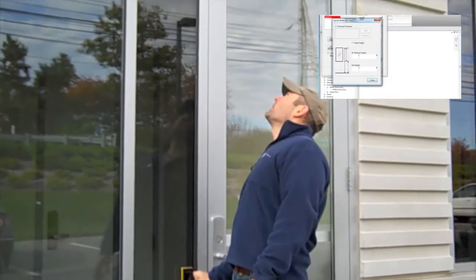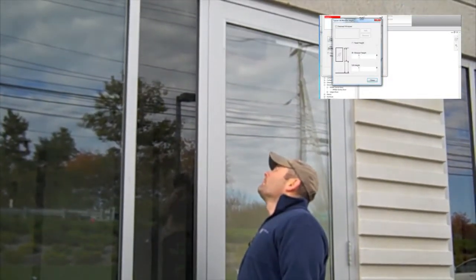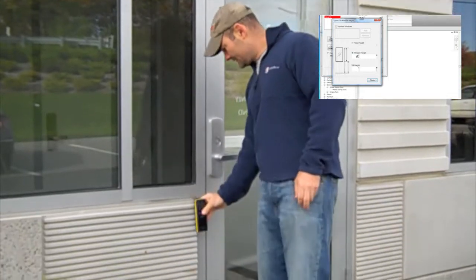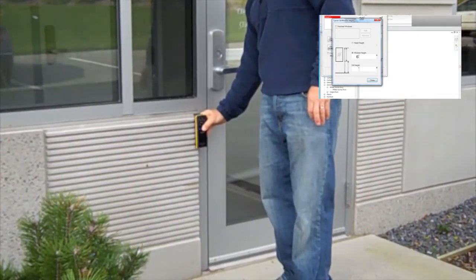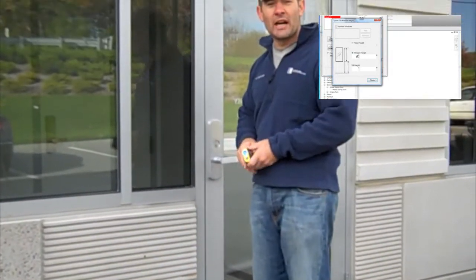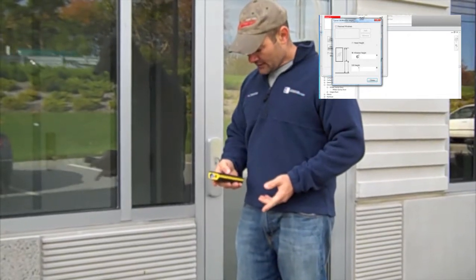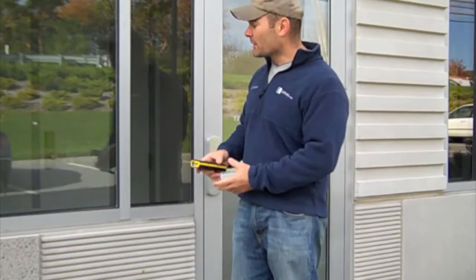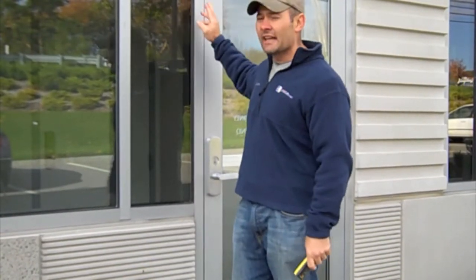We have the dialog box opened up, and I have the height here. I'm going to enter it, and now enter the sill height. We're using the concrete slab right below me as a proxy for the level 1, and we'll enter that as well. So that is entered, our first typical sill height and head height for the windows. We're now going to show you how you can get it from the tripod, from the exterior, and from distance on the building.